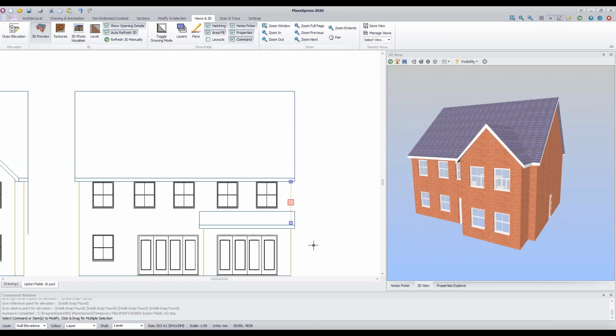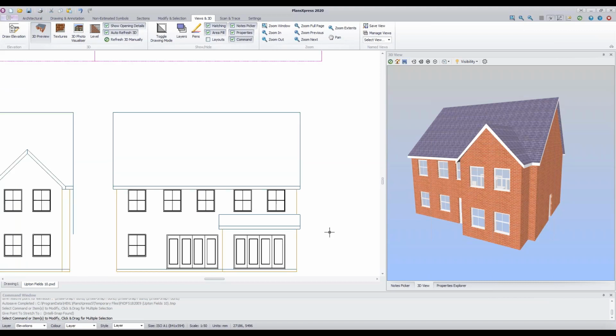So if I click on that line to select it, then using the handles, I can click on the handles at either end and use those to move the ends of this line for the wall. So I'm going to click on the bottom blue handle, move it up until I find a perpendicular point or intersection point where the wall meets the roof, and then click to trim the line. Click anywhere else on the screen to drop it, and you can see that elevation is looking pretty good now. Okay, notice also I've got this line on my front elevation.